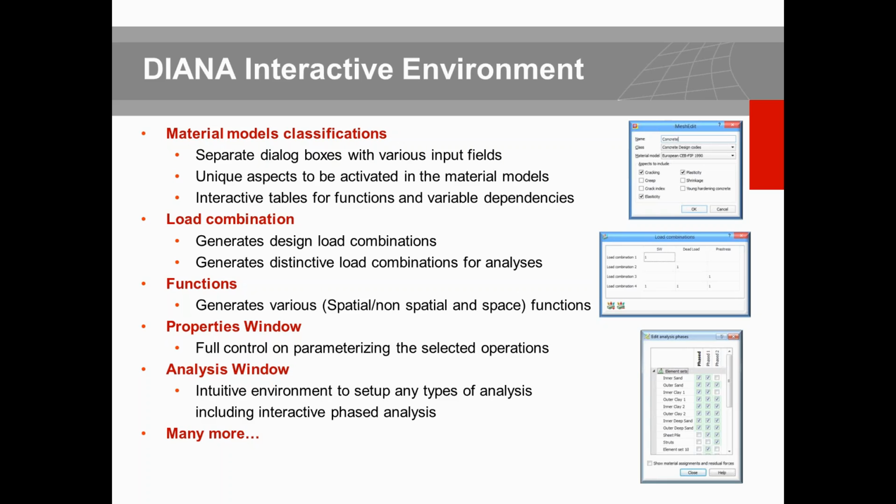Load combination is another interesting and useful feature from the design aspect as well, and also from the nonlinear aspect. So you need to set this load combination before performing the analysis. Functions we discussed already. Property windows enable you to manually control the parameters and change them based on the selection of the multifunctional window. And indeed, for the analysis window, there is a very interactive approach, especially for the phase analysis, that enables you to deal with the complex or various number of construction stages that are required for your analysis.